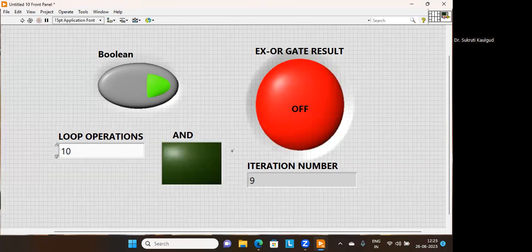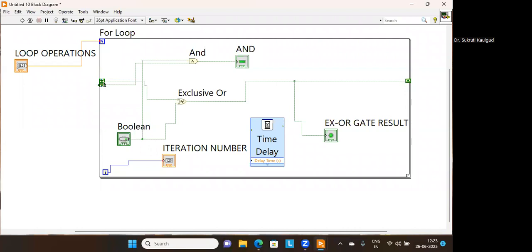Okay, so we can copy the value of any iteration. You see that the value of the second iteration I gave to one input of the AND gate, and my AND gate operation turned on. If you want the third iteration value, drag it more and take the third iteration value and use it for your purpose. So if you want serial input serial output, SISO, use one shift register. If you want a second iteration value of the shift register, you can actually trap that data.